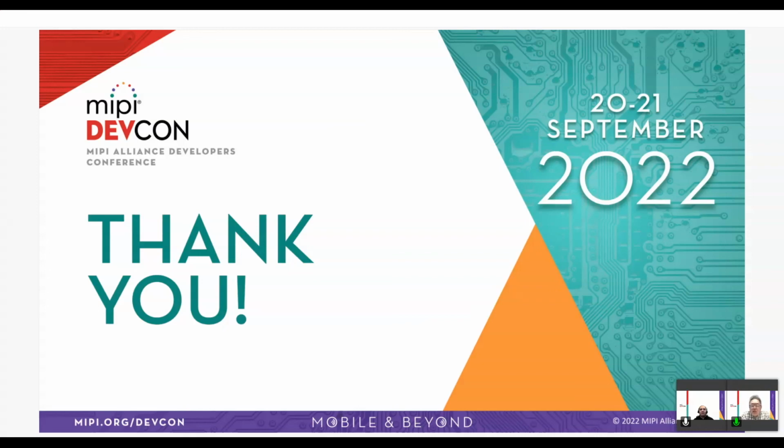Okay, so you spent a lot of time sharing about MIPI D-PHY integrating into FPGA with CSI and DSI. What other MIPI PHYs do you see gaining traction for sensors and displays? Yeah, in addition to MIPI D-PHY, we have also C-PHY. It's used independent alone or also used as MIPI C-PHY D-PHY combo. We have seen increasing interest in this IP over recent years, targeting, of course, both camera and display applications. In this particular presentation, early on I showed the Synaptics virtual reality chipset. It has been deploying C-PHY and D-PHY combo, and that was a display application. Of course, in camera and sensors, C-PHY and D-PHY are also widely adopted.